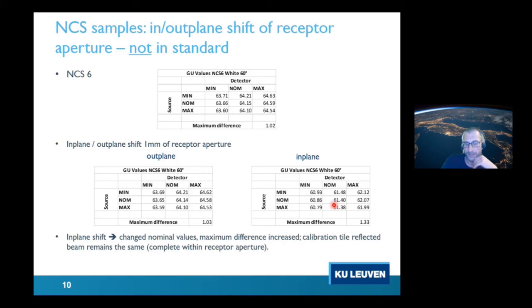So this means that with these tolerances in place, if you shift your detector by 1 millimeter, it already makes a large difference. If you look at commercial gloss meters, one could expect that if they don't position these apertures quite perfectly, then you can have such differences, which is basically what Fredrik also saw when he did the study and comparison between the different gloss meters.